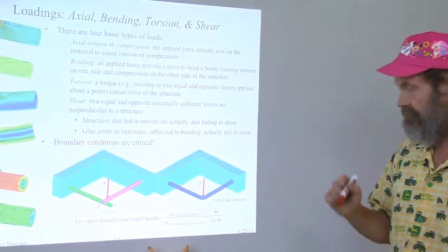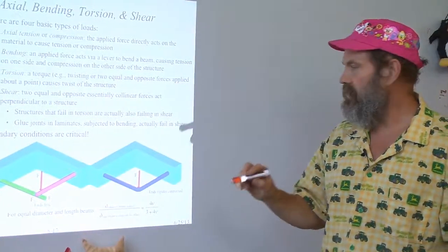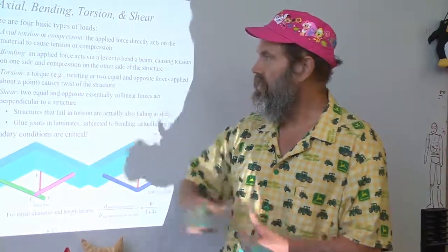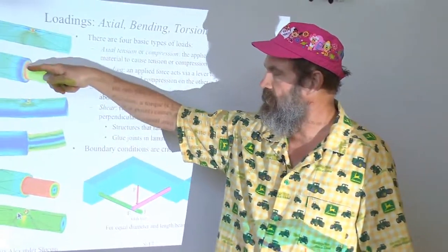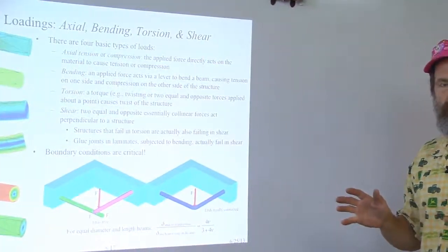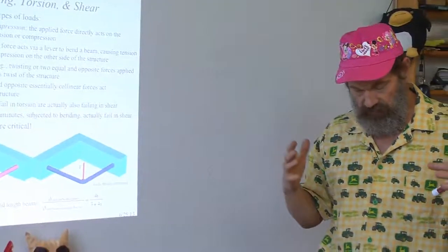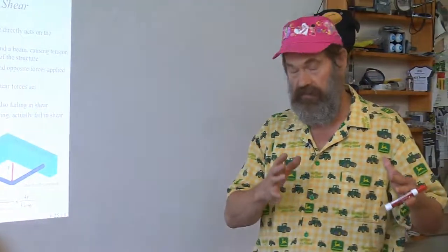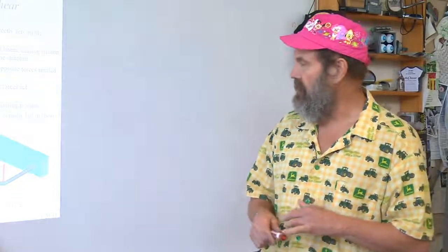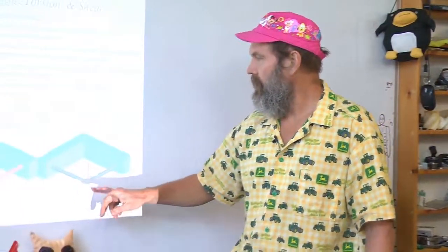What's happening? The key is thinking about boundary conditions on your structure, because at these levels of detail, it may actually cause a fairly large change when you go from the broad concept layout to the detail layout. So for example, look at structural connection issues.